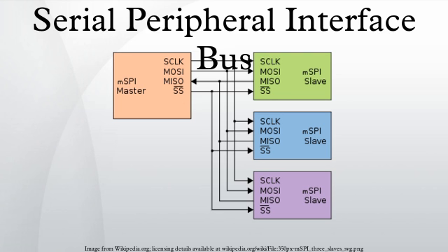Pros and cons of SPI. Advantages: full duplex communication in the default version of this protocol. Higher throughput than I2C or SMBus, complete protocol flexibility for the bits transferred, not limited to 8-bit words, arbitrary choice of message size, content, and purpose. Extremely simple hardware interfacing, typically lower power requirements than I2C or SMBus due to less circuitry, no arbitration or associated failure modes. Slaves use the master's clock, and do not need precision oscillators.